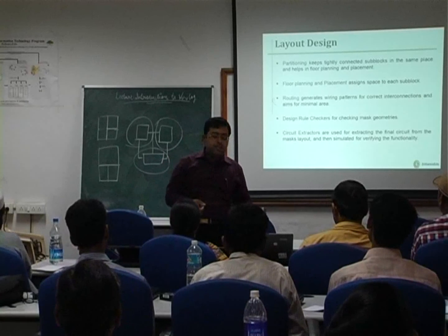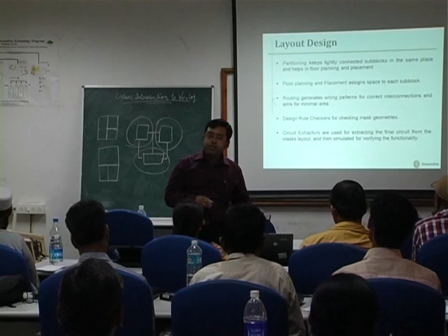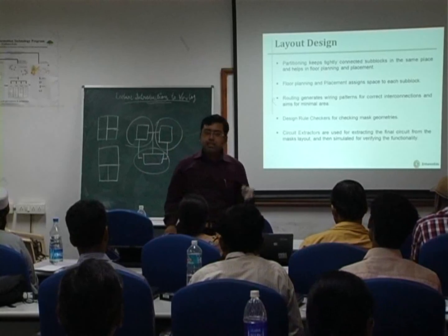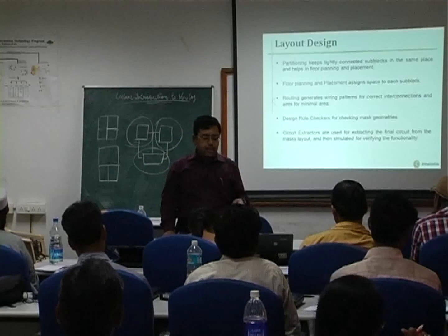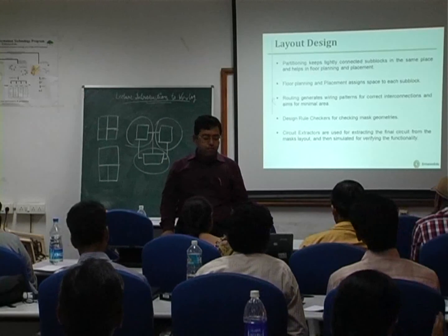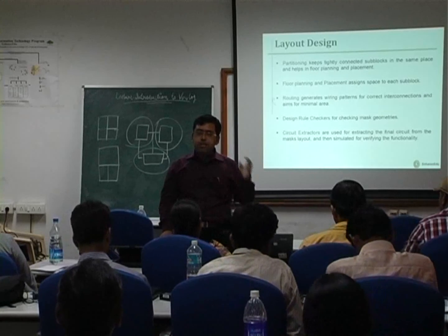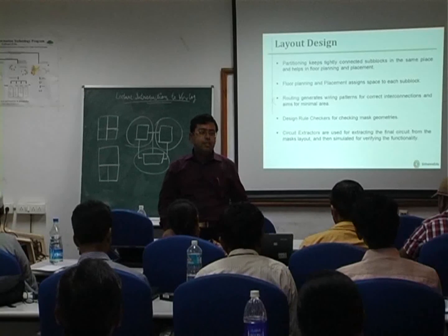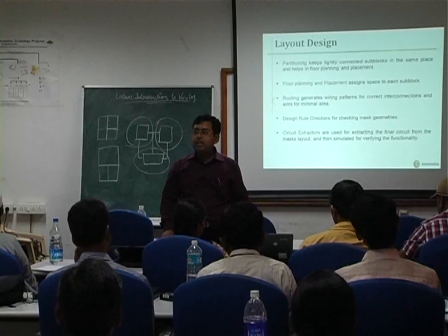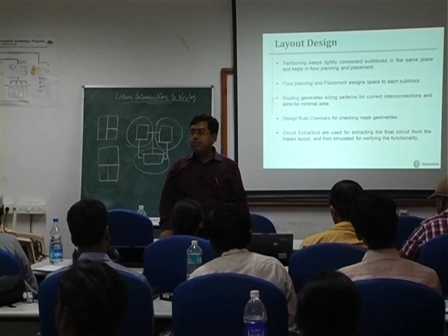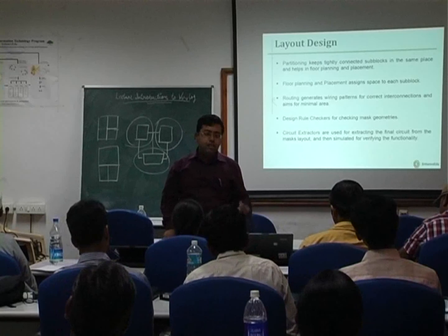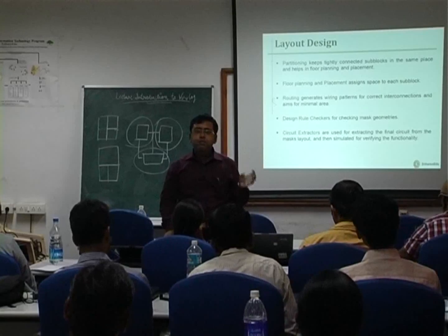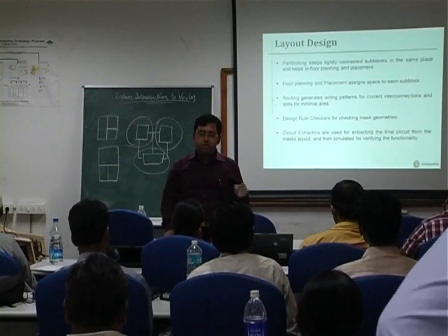So there are design rule checkers for checking the mask geometries, and we also use circuit extractors for extracting the final circuit from the layout, and then we simulate the circuit for verifying the functionality. So once you design the layout, you use the DRC to see whether any design rules have been violated or not, and then after the circuit has been extracted, you do the LVS to check whether the layout being designed corresponds to the initial schematic or not.